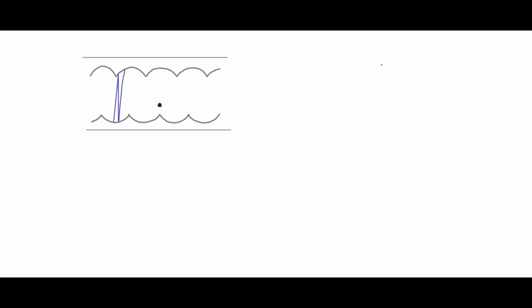After correction, the carrier should follow in this fashion, going up and down in this fashion, after you add the triplen harmonic to the carrier. How do you do that? Let me mark off these portions. This portion can be removed.